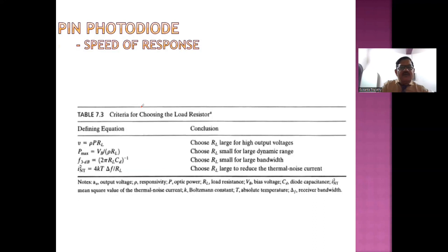Then next we will try to understand another structure which is similar to the photomultiplier. I have mentioned that the vacuum photodiode is not efficient, in the sense that the current produced in a vacuum photodiode is very small. Whereas if you use a photomultiplier, then the number of electrons can be increased, and therefore the current which will flow in the external circuit is m times more than the current in a vacuum photodiode. As I've said, m is delta to the power n.